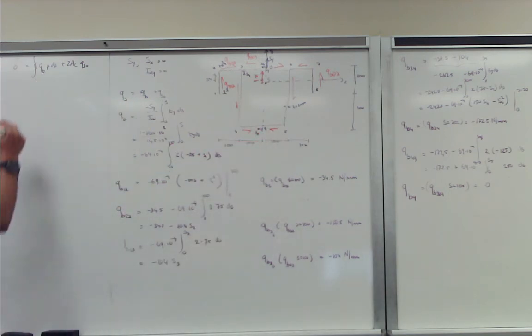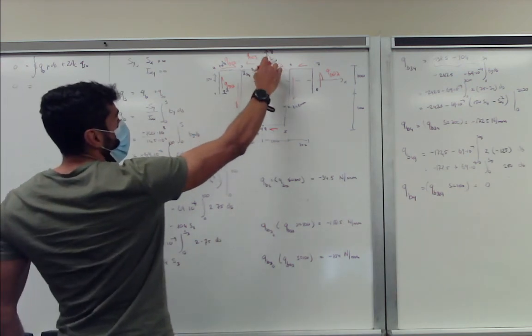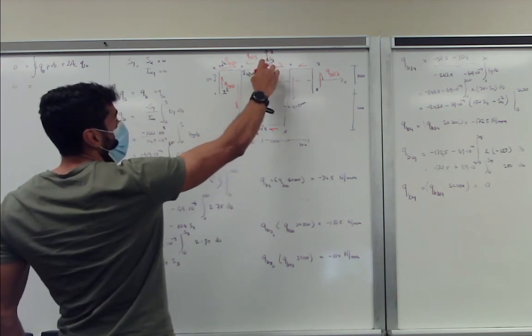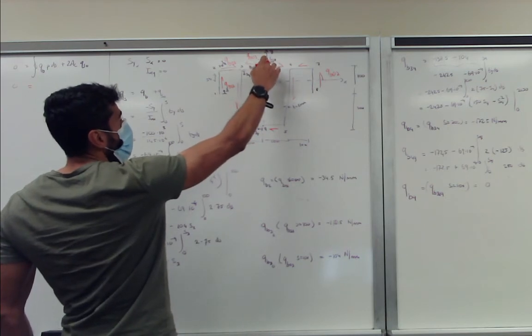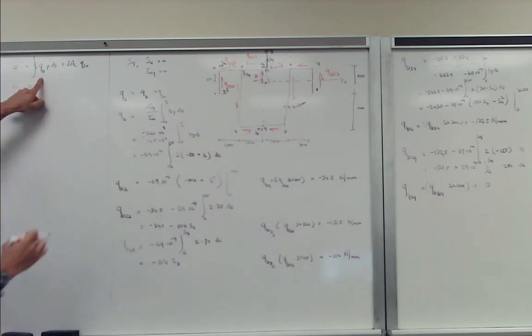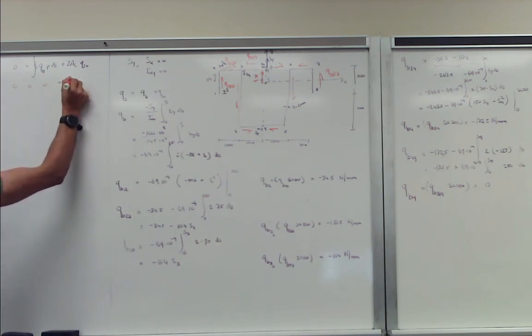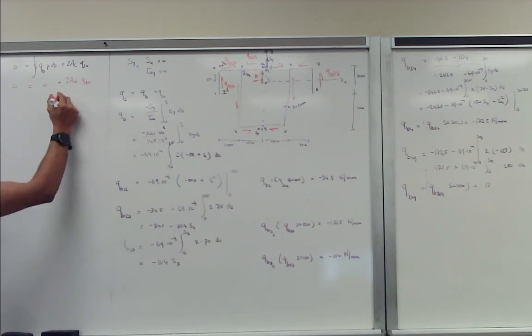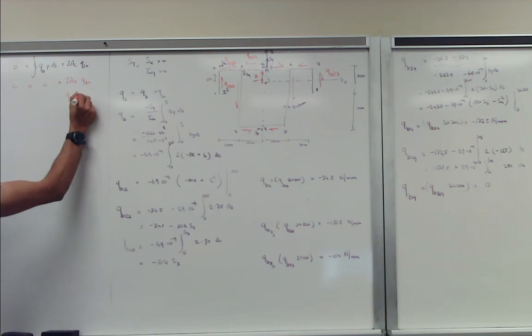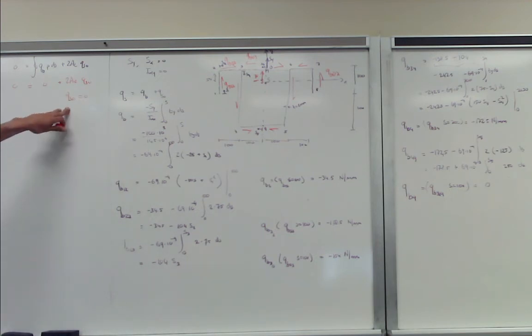So if we go to this equation, we now have 0, because the shear force goes to the point of our moment origin, or the location where we take the moment around. So that one has no arm. All the open shear flows basically cancel each other out at 0. So this is 2 times the enclosed area. This cannot be 0, so therefore this must be 0. So q is 0 in this case. Without doing any calculation, you can determine that it's equal to 0.